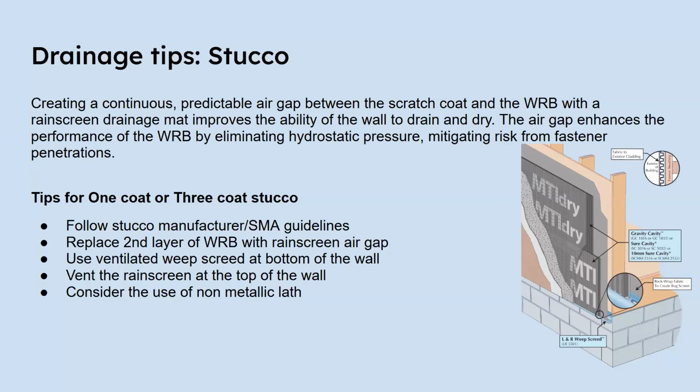Contractors are finding that this is easy. It's a lightweight product. It's labor saving. It saves time. And again, the non-metallic lath will be less susceptible to rust and degradation, especially in climates where you have a lot of rain or salt air.